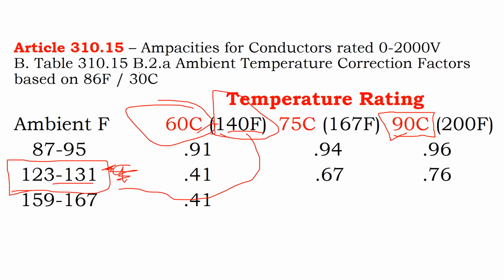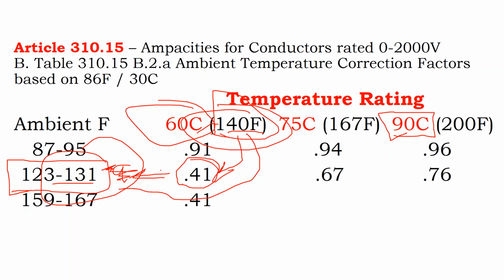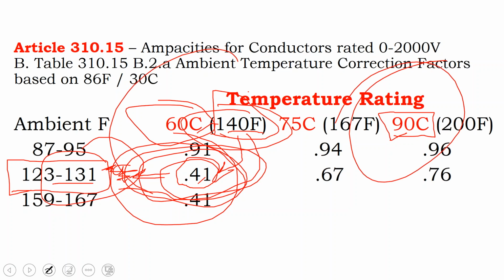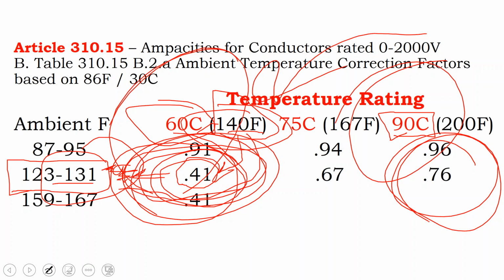And code is concerned about determining if it's a danger or not within reason. They're not taking on the liability of your own personal design practice. Well, no, you can use this cable that's rated for a 140-degree environment in a 130-degree environment, and they give you a fudge factor to say just derate the amperage rating of the wire by 40% so that the heat from the electricity does not become a problem. Well, guess what? If you use a cable that's rated for a 90C environment instead of a 60C environment, it's not up at the top of its temperature rating yet, and so that 40% derating is only a 25% derating for your higher temperature wire, because it's listed and it may have a better jacket for those higher temperatures.